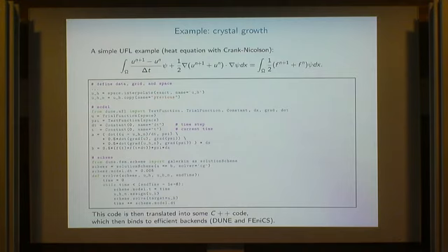Right, so what do we define? In the data, we have to define the domain, the mesh. We have to define a finite element space on the mesh. There are shortcuts for that, mostly one-liners. We need some finite element function. There was a problem where we had the exact solution underlying, so we initialized it with the exact solution. And this is going to be the UH at the previous time step. Again, it's a finite element function.